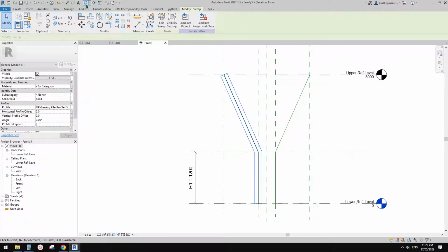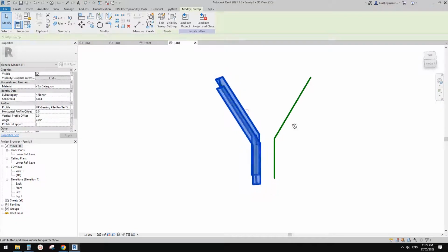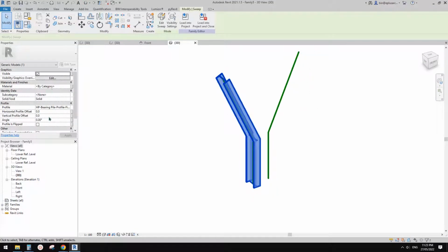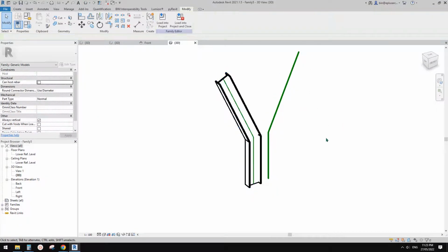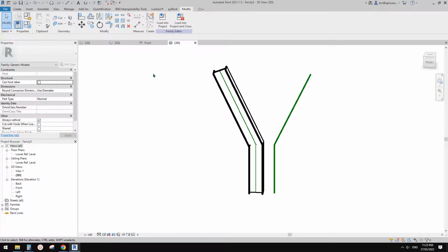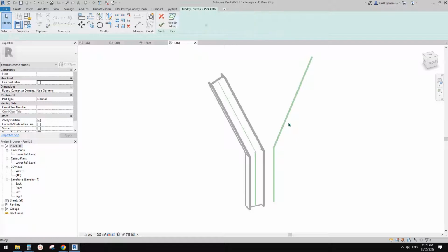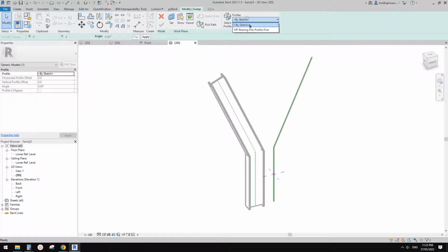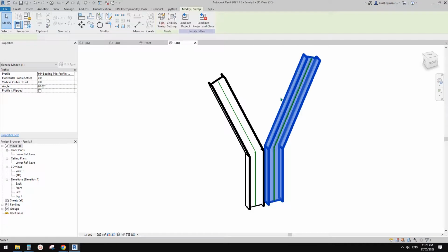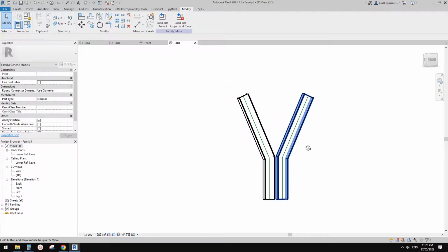And you will see, we probably want to rotate it by 90 degrees. So just go here, 90. That's it. And then to the other one. So we can do it in 3D view as well. So pick path, so create similar. So sweep and pick path, finish, profile, 90 degree, apply, okay, finish. So now we have this one.